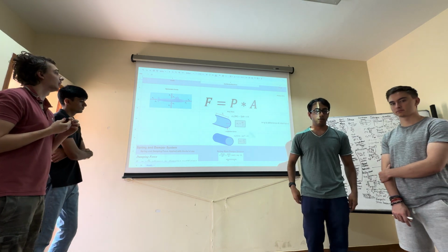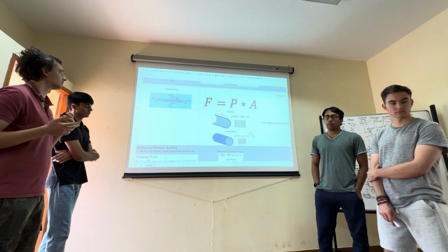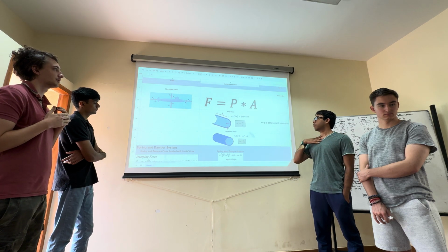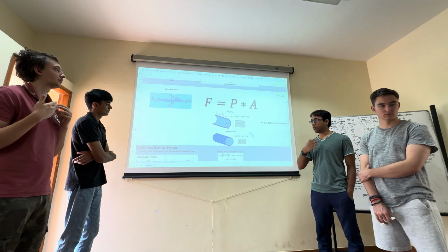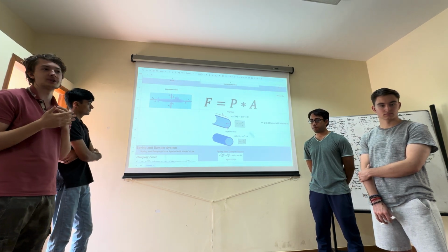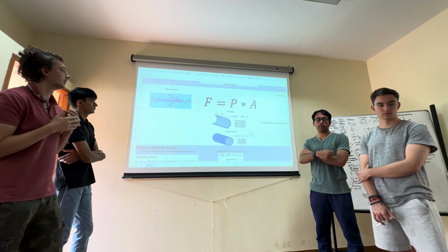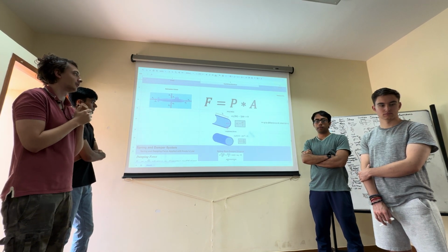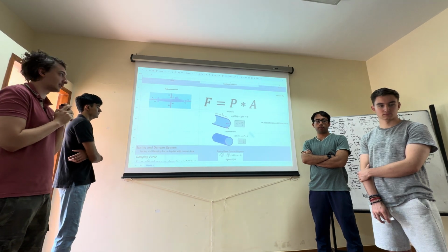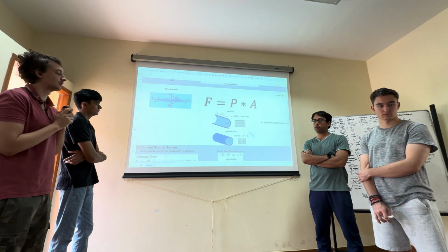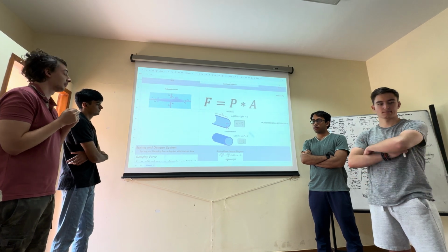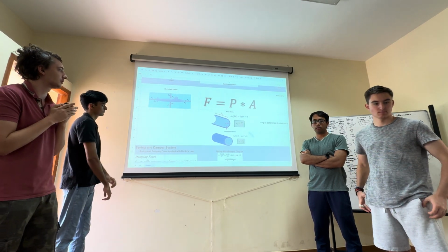So now I'm going to talk about hydrostatic forces, which are caused by incompressible fluids. We can relate hydrostatic forces to stress, and stress being pressure, by the equation of force equals pressure times area. Also, as an example of a submarine, we can use hoop stress equations, since a submarine is a thin-walled structure, mainly a monocoque thin-walled structure.